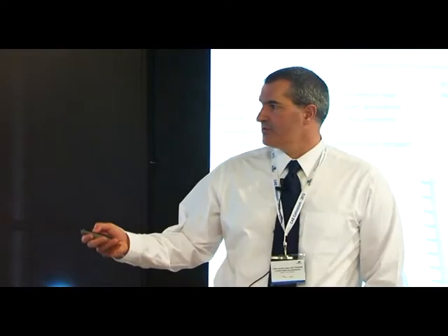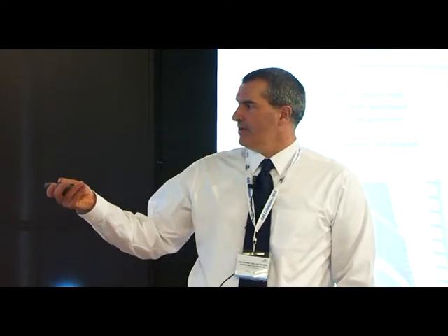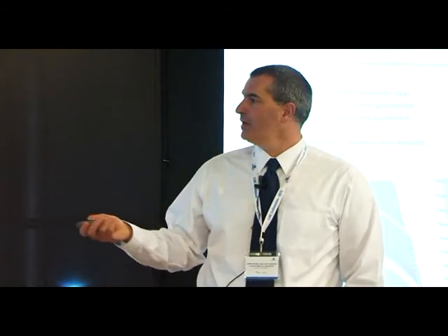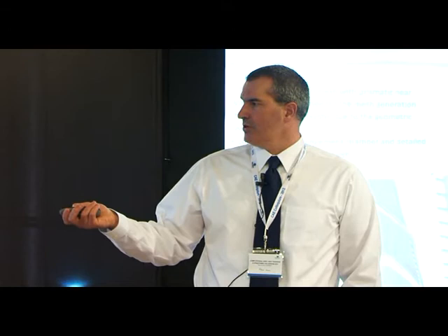So next step up for us was to generate mesh for this. And this is an example of what the mesh looked like. Again, we had detailed internal chambers for the convective cooling to understand how the external flow field influences the internal. Detailed film holes all the way through, and then details on the external surface of the blade.